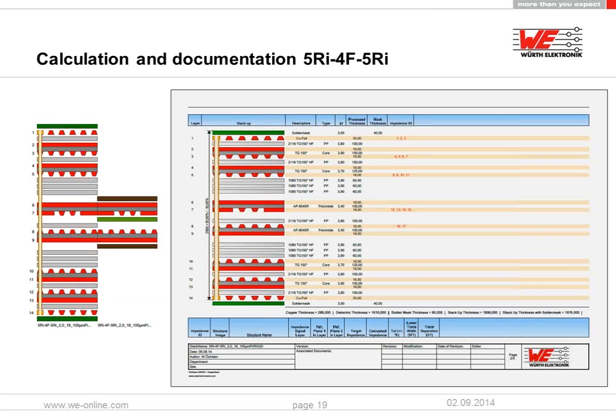So this is quite important, to have such a good documentation, so that there is no risk of using the wrong material in the production or swapping layers by accident. So it's easier to use the correct material, board thickness, and stack-up for the producer. The next thing is, you can see all the dielectric impedance, all the impedance models and the calculation.